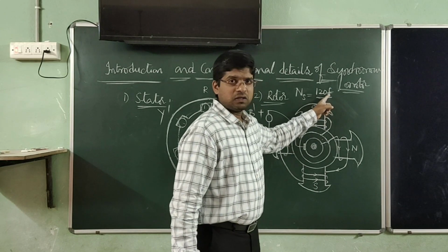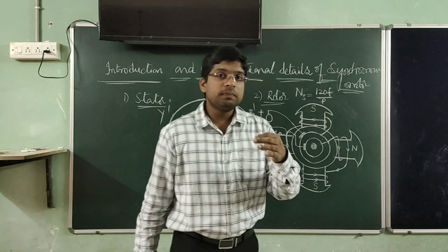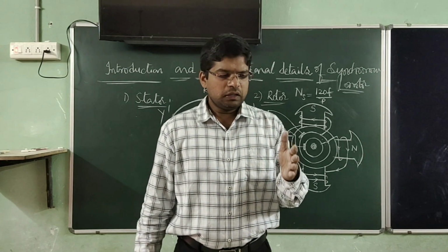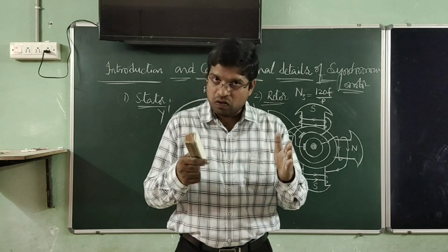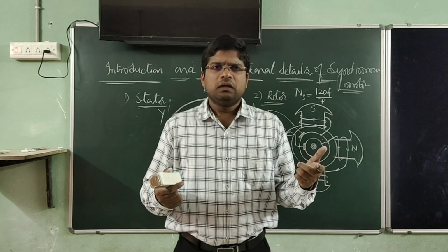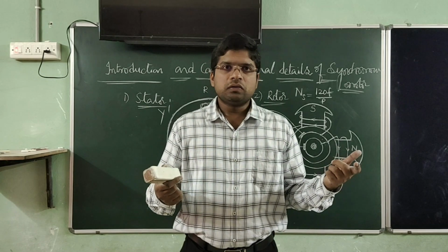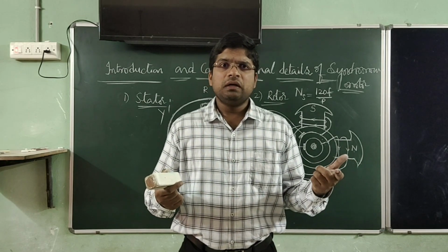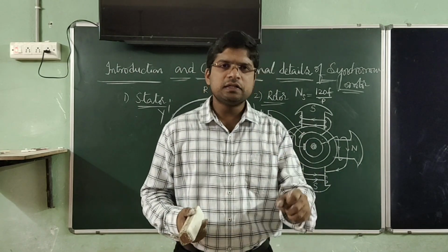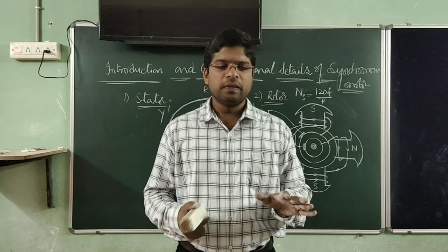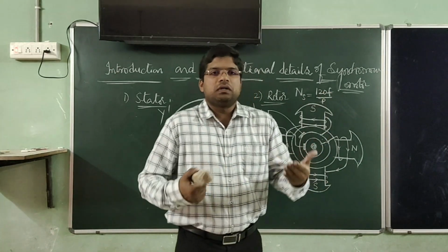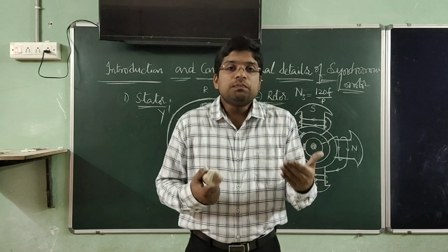Since frequency is constant, synchronous motor can also be called a motor which is running at constant speed. So this motor always rotates at constant speed only, irrespective of loads. The load may be a light load or normal load or overload. Whatever the load may be, synchronous motor always rotates at synchronous speed. The speed of the motor is always tied to the frequency of the supply given to the input.